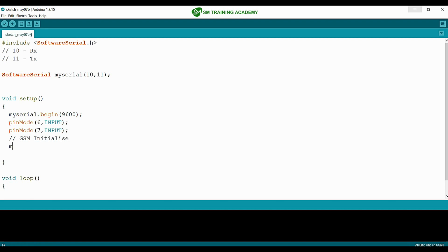I am just going to use the same object of serial. And I am going to call the function write for writing the AT command, AT \r\n. So you can pass a string of data right over here to the write function